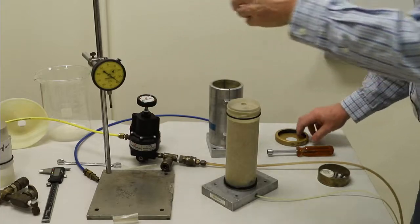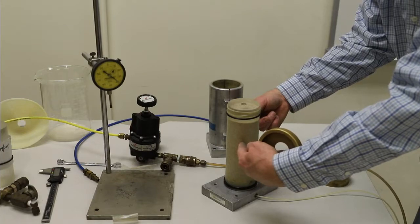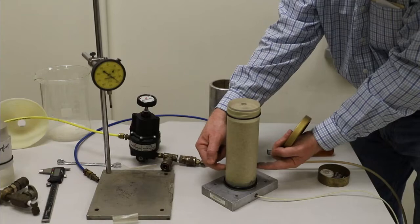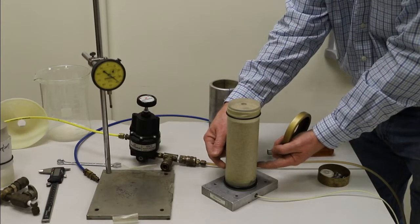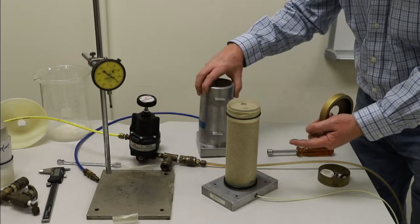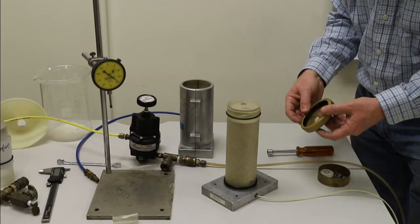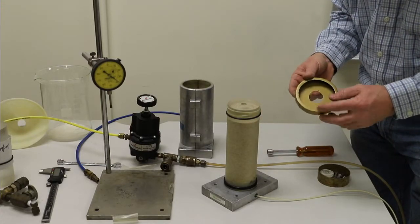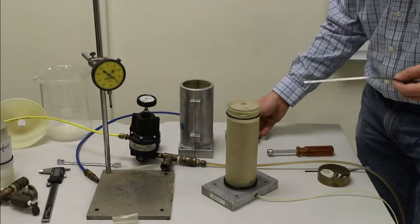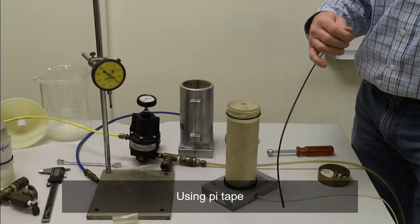And there's a couple ways you could do that. If you had calipers, you could measure the diameter in one place, and another place, and another place. They'd all be slightly different, probably. And some of that is because there'd be a slight variation with height due to the mold, but there would also be a variation because the mold is not perfectly circular. And so you'd want to take a bunch of readings and average them in order to get a diameter.